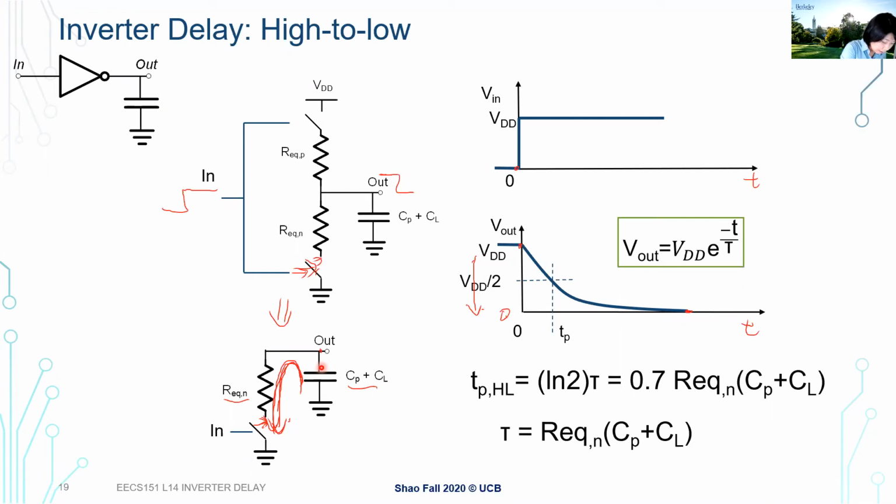If you look at the circuit, there's no reason to remember any equations. But if you think about the way my voltage changes over time, this is basically an exponential decay function that can be represented here. If you're interested, you can analyze this RC circuit at a very high level. Once you first start discharging, at the very beginning my output is VDD.